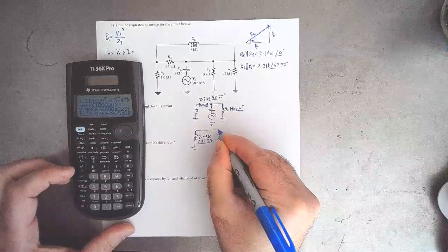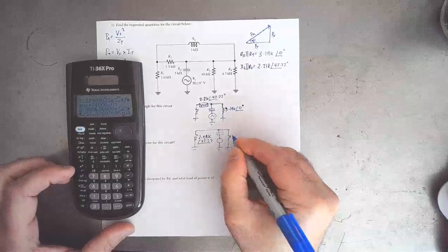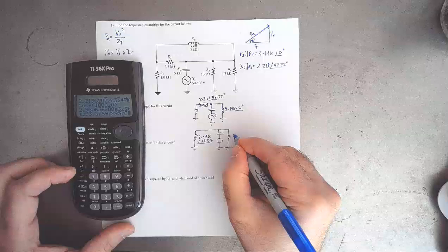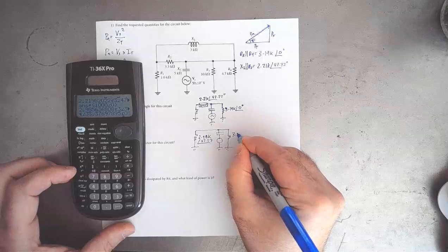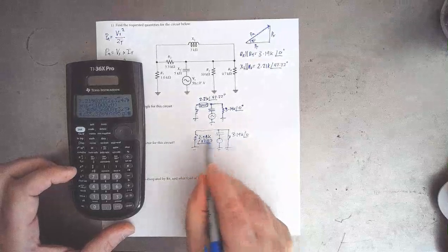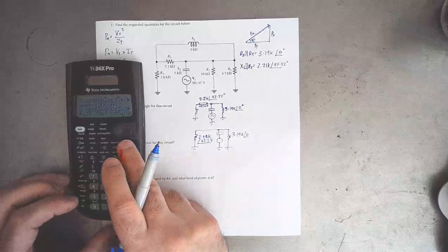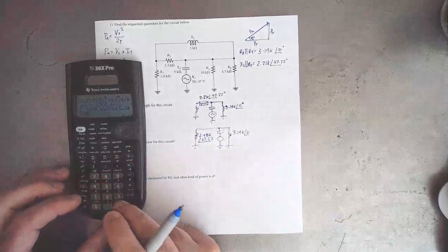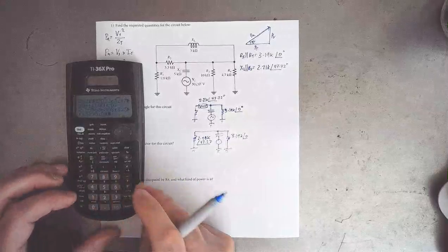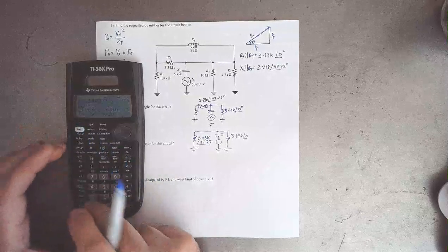And finally, we've got this right here. And I'm just drawing resistors, even though these are complex impedances. So 3.19K at 0 right there. Well, you notice that that's in parallel with this. So this and this impedance are in parallel. So let's do it. Product over sum here. So 3190 at an angle of 0 times 2980 at an angle of